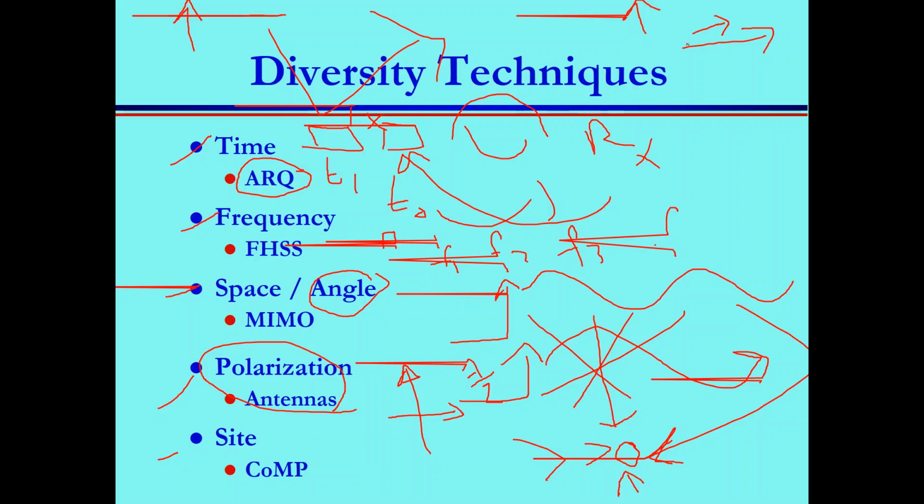How does the polarization change? Basically the incident angle, the reflection angle, the inclination angle. This is due to the environment and characteristics of your medium. That's why in 2G, 3G, 4G, we don't care much about polarization. We transmit it, and of course we receive it. But we really care much about millimeter wave, when you don't have too many reflections, and you must be careful about that.